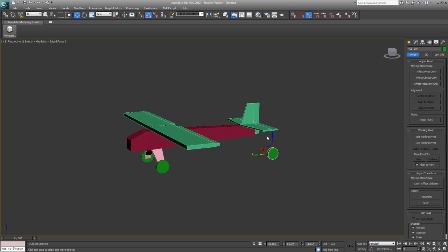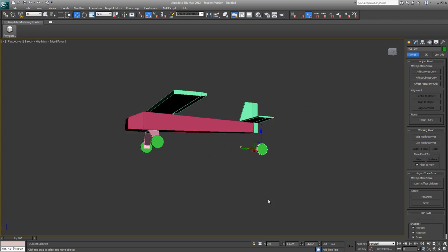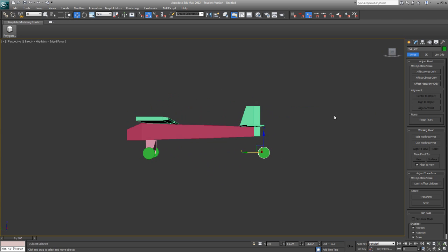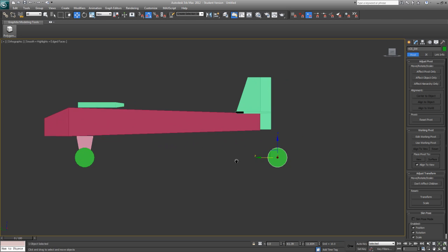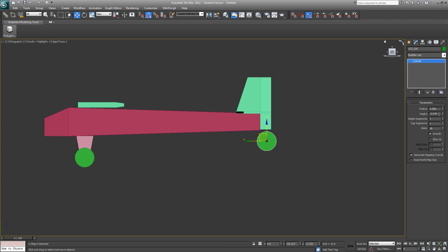Click OK. Quick way to get that to the center of the fuselage is right-clicking on the X. Boom, it's centered under our fuselage. Go to a left orthographic, or I can click this little icon at the top. Click left, and then U. I'm in orthographic, and I want to put this underneath my rudder. And going back to the edit, I can change the radius. Make this more appropriate for a tail dragger. Simple little tail dragger. Move that up till I'm happy.